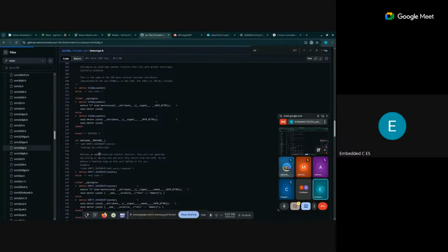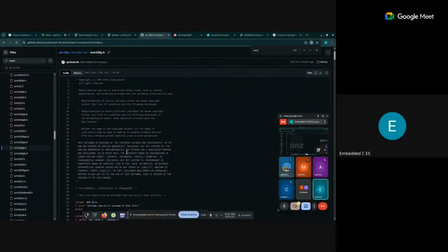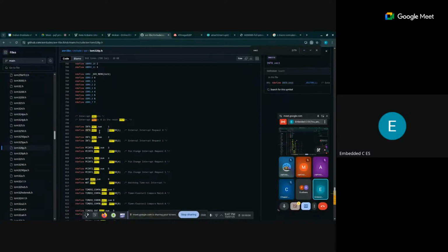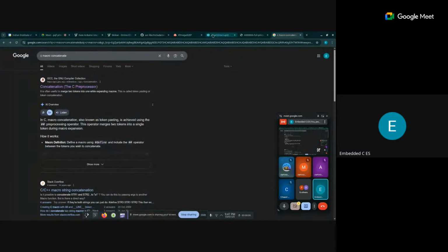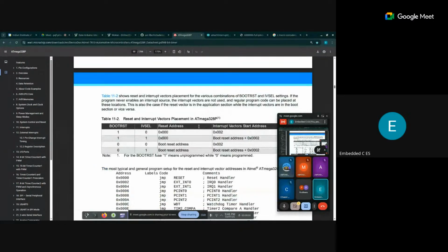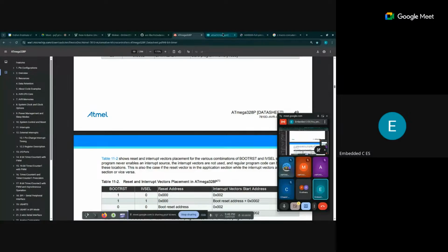328. See, these are the interrupt service vectors. For each interrupt, there is a number associated with it. And this vector, this is what we want, the external interrupt request vector. So given the number, you can use the vector like this. This vector is basically another macro which converts the interrupt number. As you can see, there are numbers associated with the interrupt and also things like that.